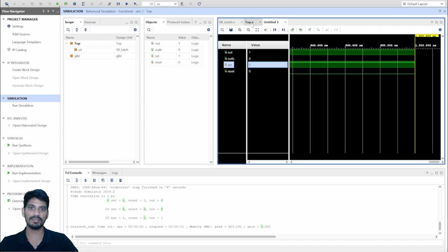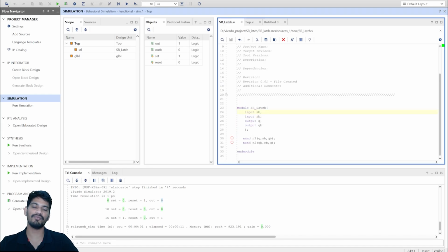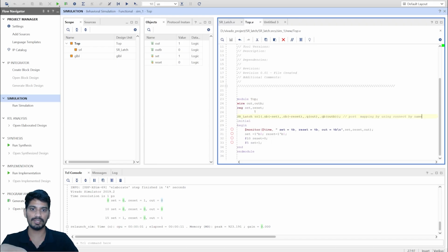So with this, we have shown different kinds of operators that exist in Verilog, and how to use a module, and how to use a test bench to test the module, and how to give different test vectors, and how to use different system tasks like dot monitor, dot time, and how to use data types like wire, register. We have covered almost all the basic concepts.